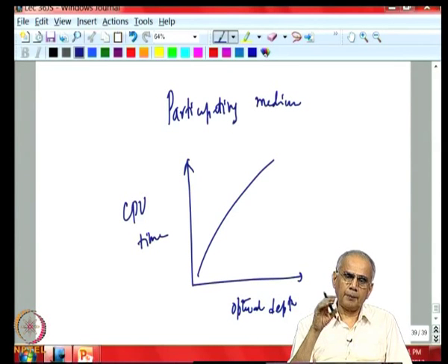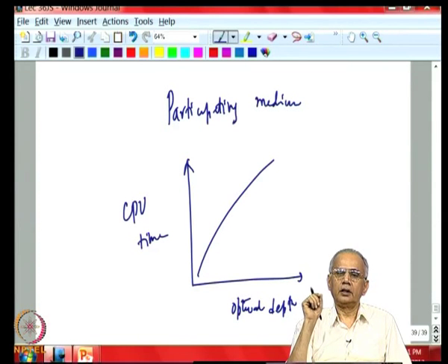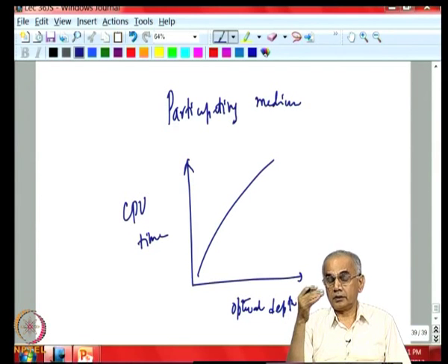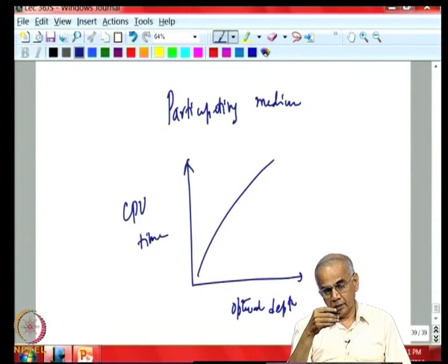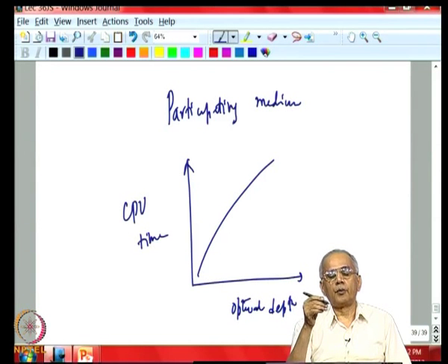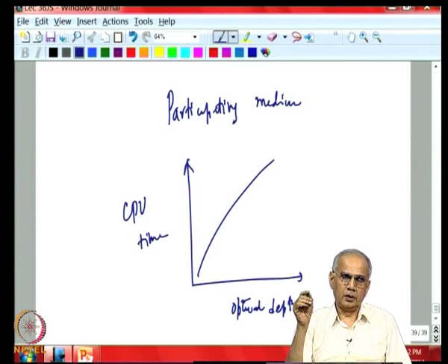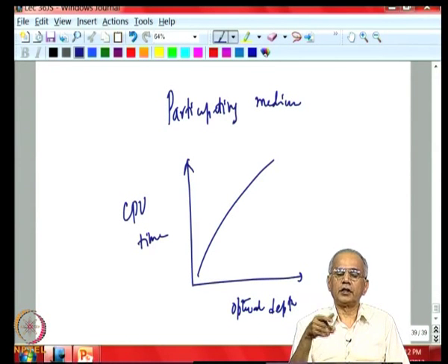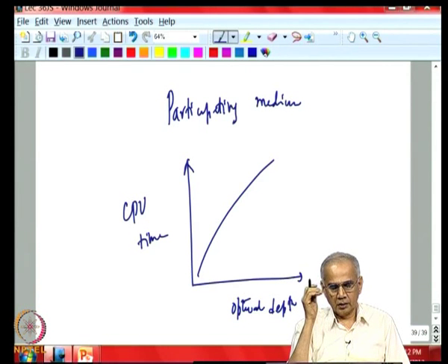We saw a large number of examples in this course in which we use traditional techniques only, about the behavior of a photon being similar to that of a fluid undergoing conduction, provided that the photon mean free path was small compared to the length scale of the problem. And similarly, we saw that when you have very small photon mean free path in a gas, you can use a differential approximation to solve these problems.